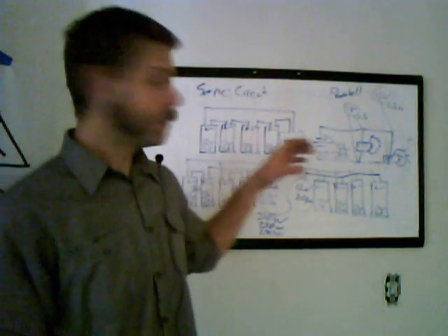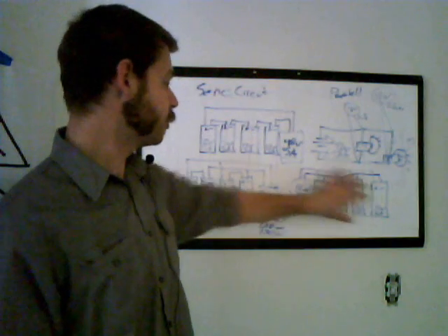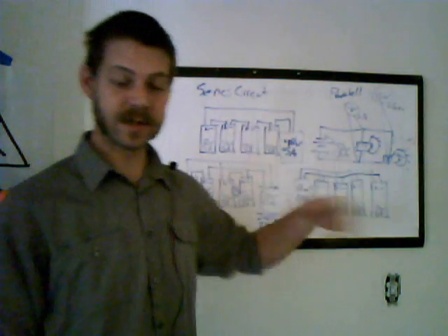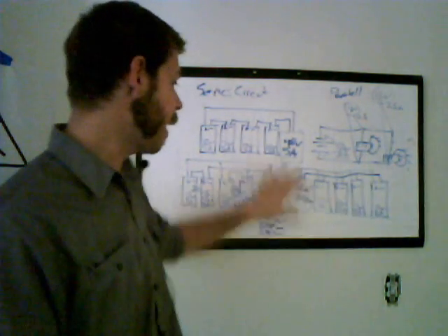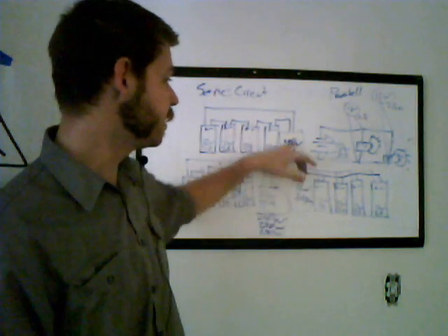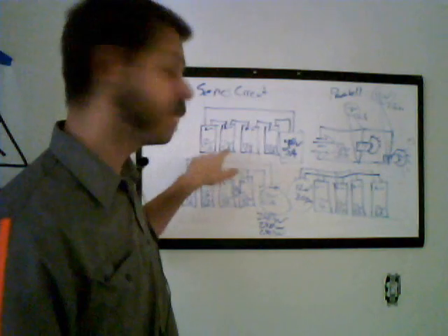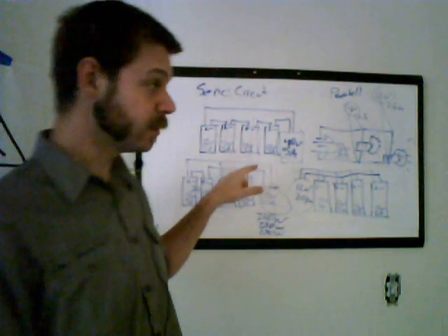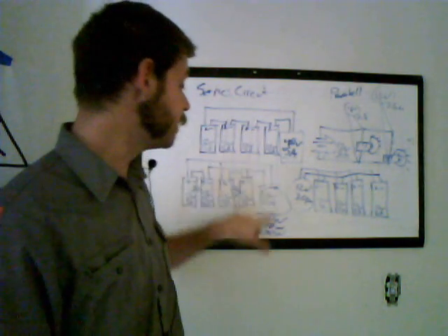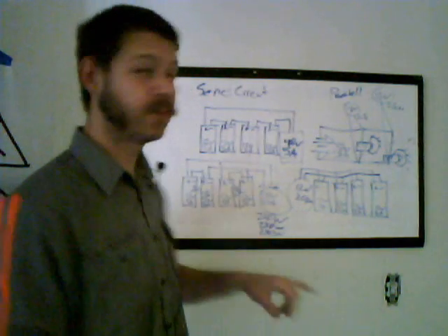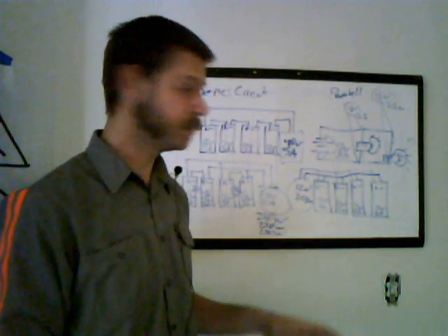It's useful to use wattage to measure panels and to measure how big systems are going to be, because no matter how you wire them together, you can get different voltages and different amperages, but these 4 12 volt 5 amp panels are always going to give you 240 watts, no matter how you put them together.